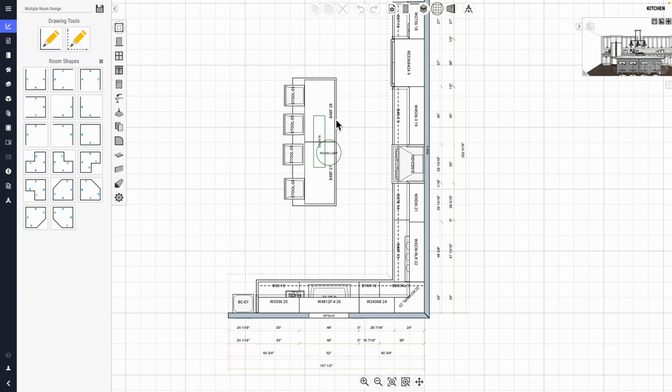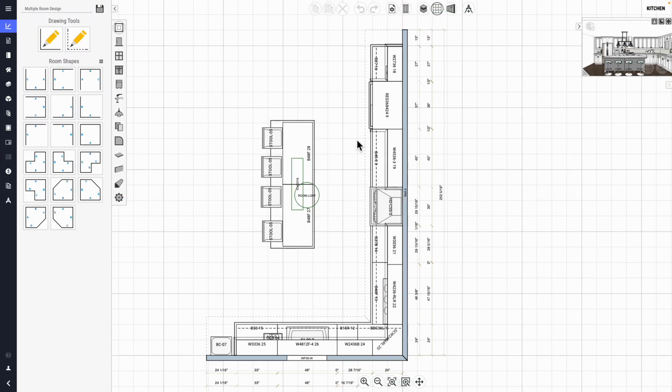Speaking of CNC, the last feature that comes with 1.3.2, the last major project, is the ability to natively host negative coordinates within our CNC output, so that you no longer have to do work coordinate offsets or maybe change the overall origin of your CNC setup if you have an unusual coordinate system.